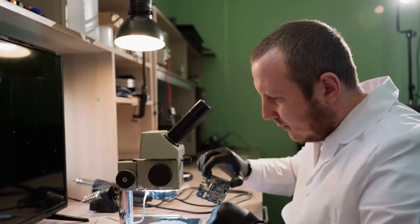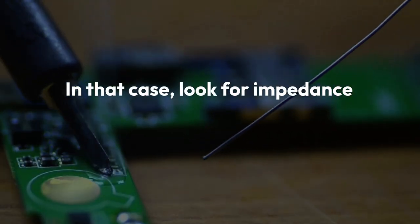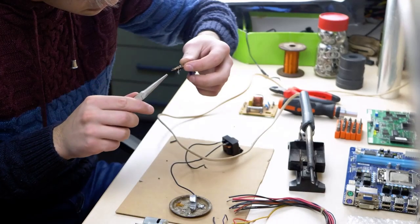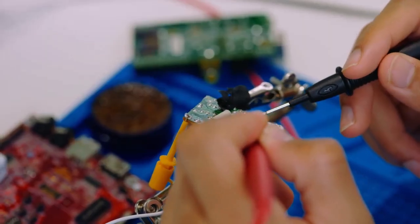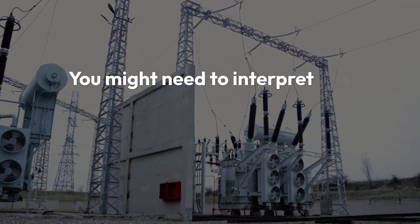What if you can't find ESR explicitly listed? In that case, look for impedance, Z. ESR is a component of the capacitor's overall impedance. At the capacitor's self-resonant frequency, its impedance is very close to its ESR. Datasheets often provide graphs or tables for impedance versus frequency. You might need to interpret this data.